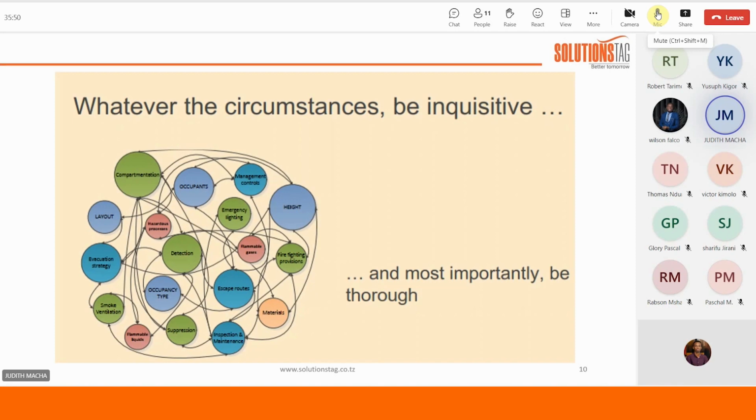Then you start with, maybe, checking the testing of the sprinkler system, starting with the testing that has been done on site, whether by engineers or those responsible for the sprinkler system. Then you check what the weekly testing reports are, what the weekly inspection reports are, and then you see what the monthly reports are. What do they say? What were they checking? Are they sufficient? Then you go down to see, okay, there are some reports produced on site, others are routine, but there are some others that have been done by specialists. Then you go down to see those routine services that a specialist or a contractor has to do to that sprinkler system.